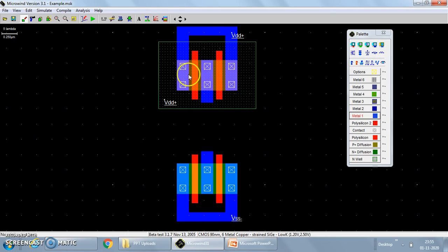See, these two terminals are interchangeable, source and drain. As per the convenience of layout designing, in this case we can interchange the terminals. Means if you assume this as a source, gate, drain, we need not again assume the same sequence, source, gate, drain. We can consider this as a drain. So from common drain terminals we take the output. So I will again extend this layer to the down side till this point. Now see, this is a source.